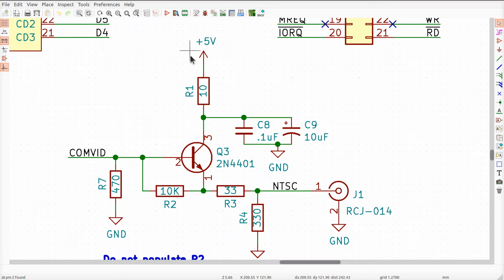Because if we have 5 volts in here and it's super noisy, all right? If this thing is so noisy that the voltage ever drops all the way down below 2 volts, which is how low it would have to be in order to cause a problem over here, because remember, the most voltage that ever comes out over here is about 1 volt, 1.5 volts. Okay, so as long as this thing's at 2 volts or greater, this circuit will work fine.